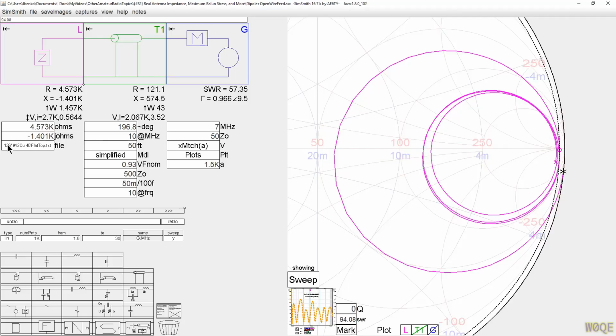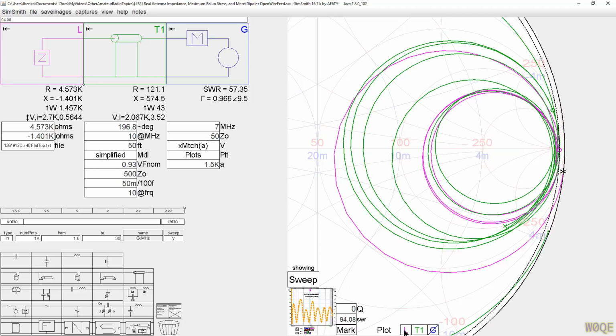And you say, of course, it's stupid to have an antenna that's 136 feet long. It's exactly a full wavelength on 40 meters, and et cetera, et cetera. So let's just keep in mind all this graph. Now, these impedances are the impedance at the antenna. If I look at the impedances here at the generator, we can do that too. We'll take away these impedances. We still see the same range of impedances.